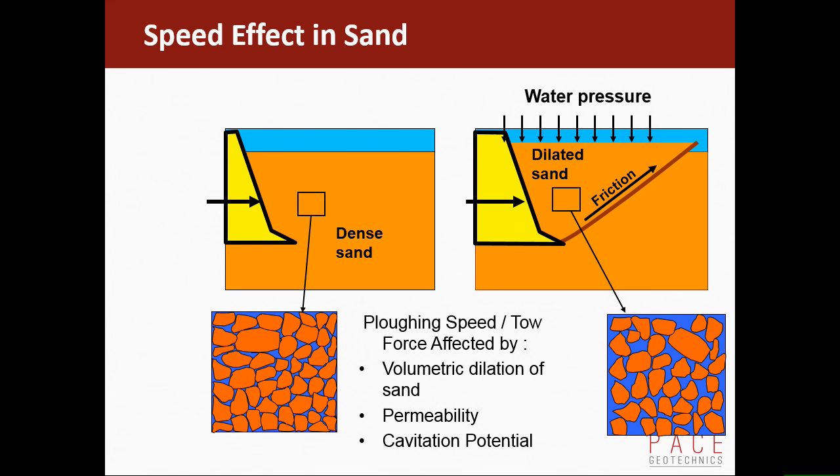Now, for that to happen, water's got to flow into those void spaces. And sand is a reasonably permeable material, but it's not highly permeable. The water doesn't flow immediately in, so you end up with a sort of force balance whereby as the plough shears the sand, it moves apart, but then water's trying to run in, and as that water is trying to run in, it's creating a pressure difference which is pushing the sand particles together.